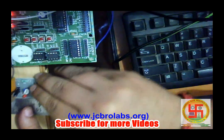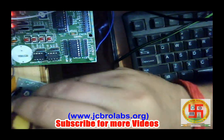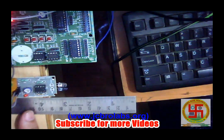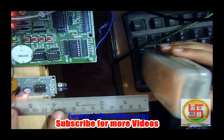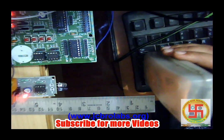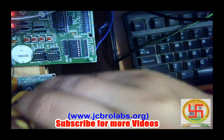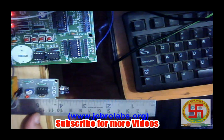We have connected the same IR sensor and provided the supply, and then we can change the distance at which it can detect any particular object by varying this resistance. Right now, if we see, this is our object, and it is detecting the object at a range of nearly 4 centimeter. Even when our object is at 4 centimeter, it is detecting the object. But if we want to reduce the range, let's change the resistance value. Just by changing this variable resistance value we can reduce the range of the object.